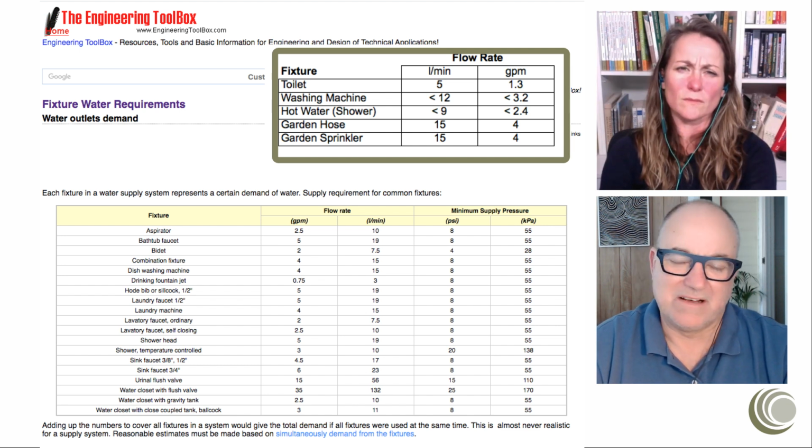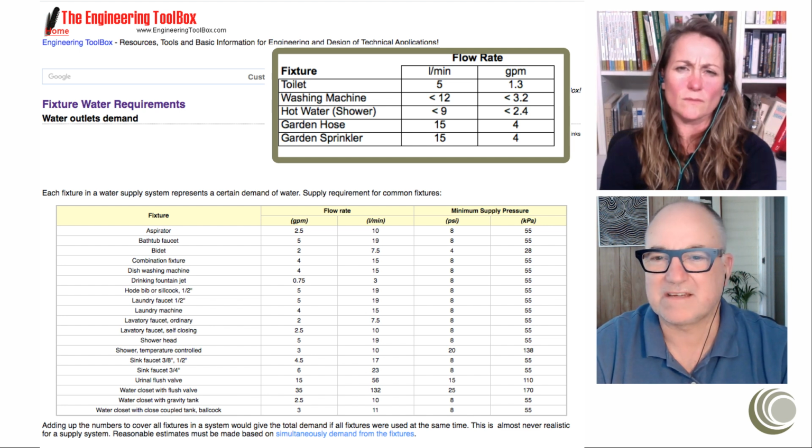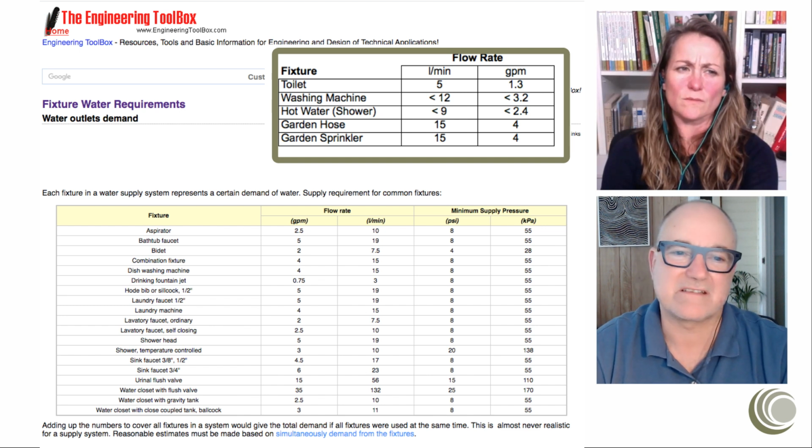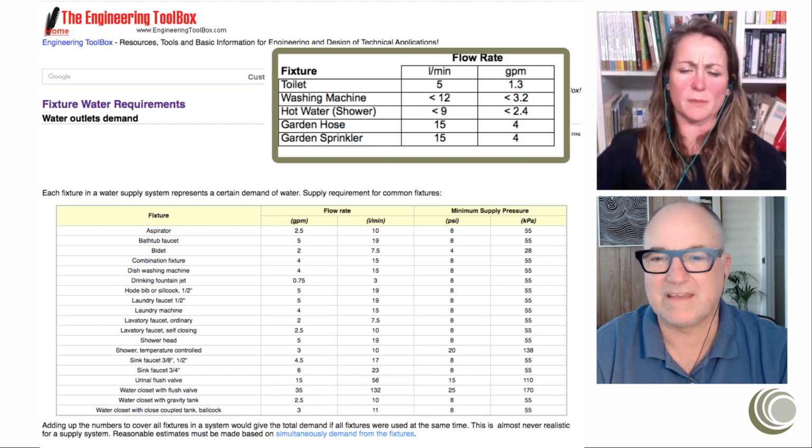We've replaced all those in my own house and others that we've advised with 32 millimeters, which is over an inch for you guys, lines, and that actually completely eliminated the majority of the friction head losses in the supply house. So the supply,